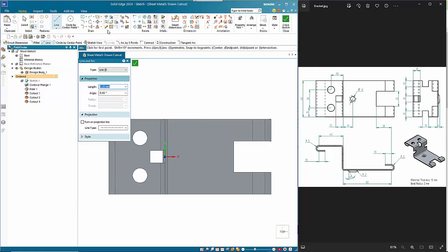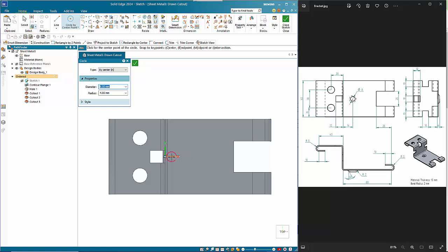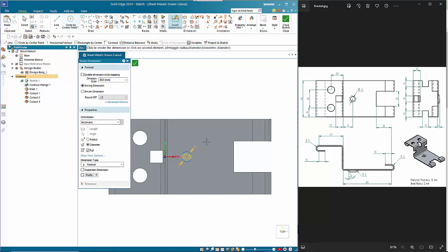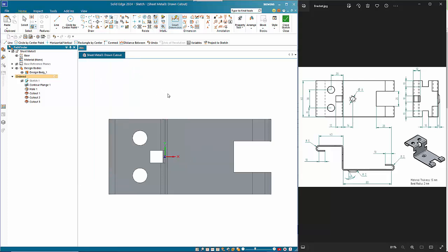and this is going to be a 8mm circle. So I will come off of that plane there. I can add a dimension, and then a dimension to the coordinate system. This one wants to be 16mm, and we'll close that.